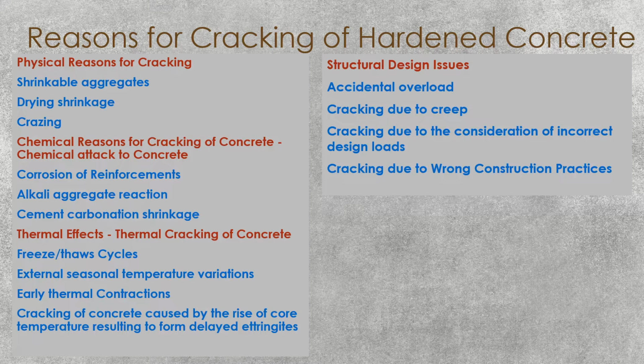Cracking due to wrong construction practices, which we previously also discussed under the physical reasons, along with other reasons for cracking of immature concrete. So we have to have correct construction practices. Curing is one of the things you have to concentrate on. If you are not doing proper curing, there may be cracks in the concrete that definitely affect the durability of the structure also. All in all, concrete cracking is very important in terms of structure and durability.